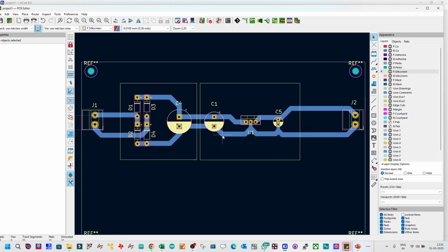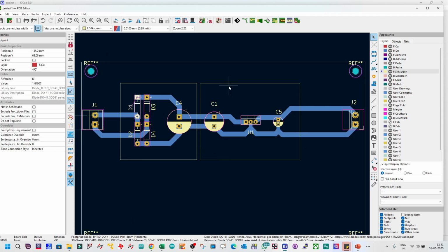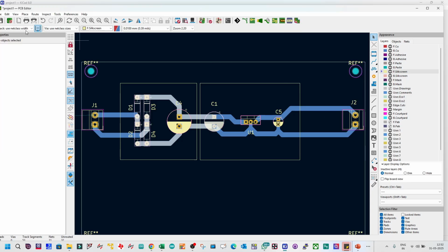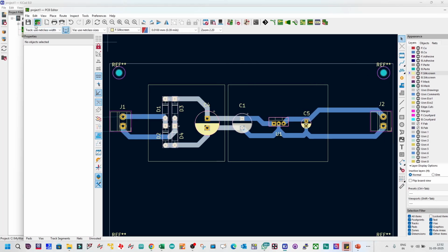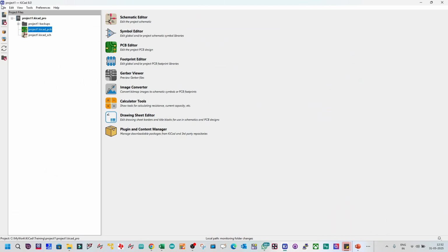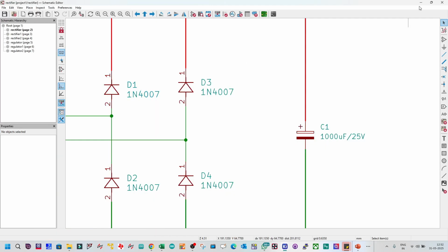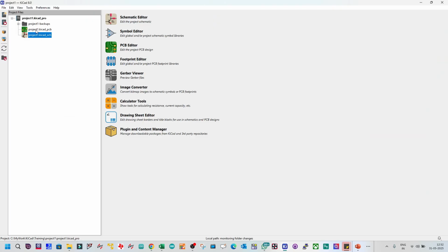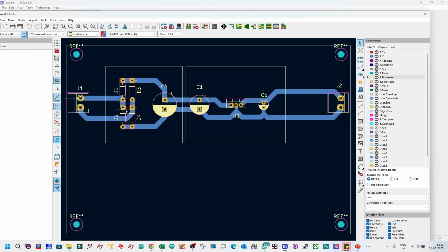Okay. So I will select any component from this block. I will go to replicate layout. And once the window is open, and the window is gone, where it is there, I have not connected any other keys. Okay, let me refresh it. Let me deselect from here. It should be clean. You should not have selected anything else apart from that component. Otherwise it will mess up.